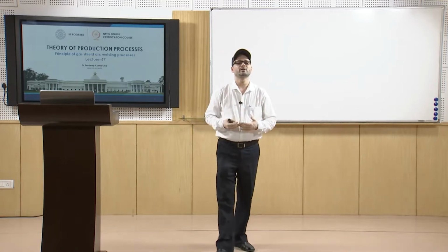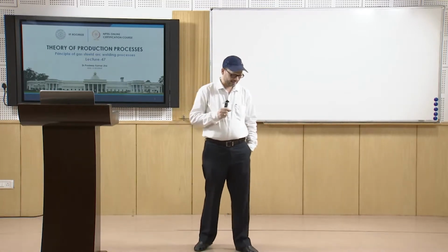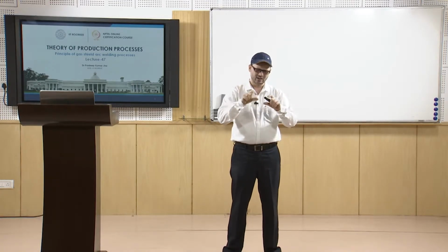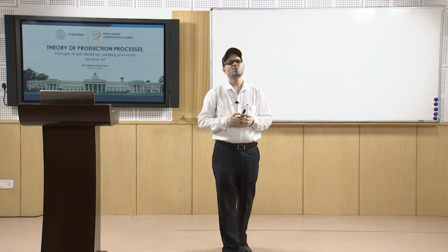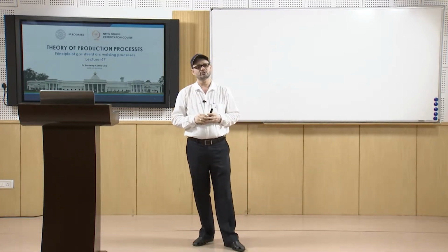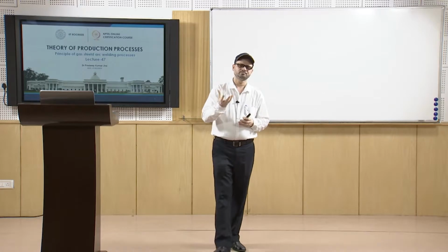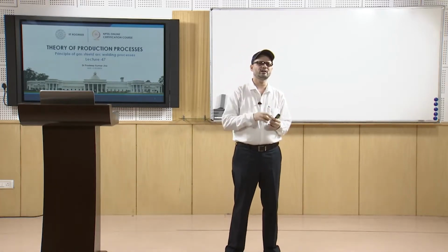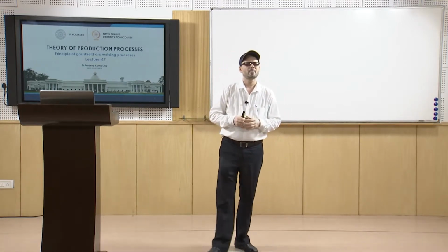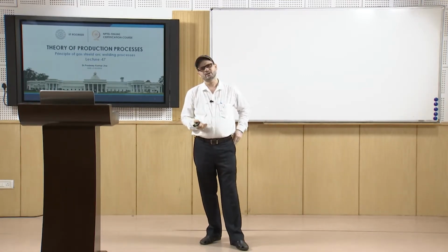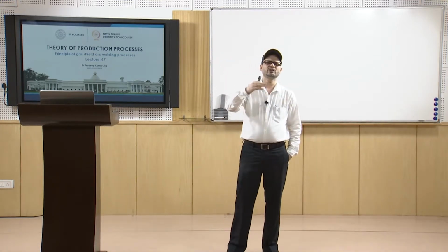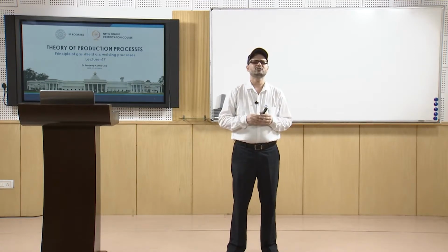Or we can have surfacing for improvement of properties. Again, since here you have the bare electrode, which is pointed and focused at the joint, a wide variety of joint designs is possible. When we talk about granular flux or coated electrodes, that degree of flexibility is not there in those cases. That is why you have a wide variety of joint designs possible.